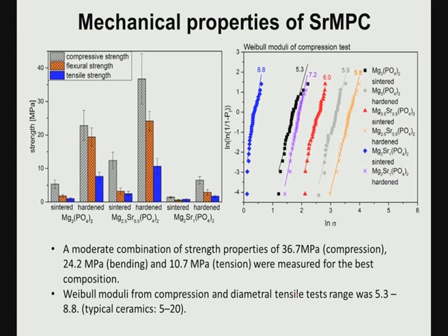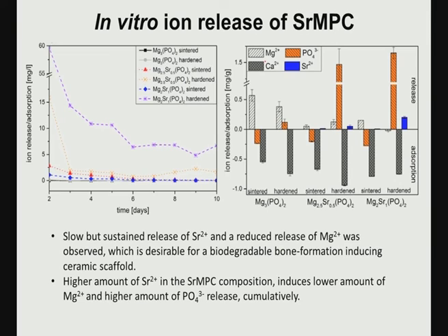In terms of mechanical properties, you can do a lot of other interesting things, and that is called the Weibull modulus. Weibull modulus means strength reliability, and you can see the strength reliability values, the m values. m is the Weibull modulus, and it is around 9 or 5. These values are very important because additive manufacturing is one of the newer techniques, so it is important to define the strength reliability of ceramics, which is a major concern for other conventionally sintered materials.